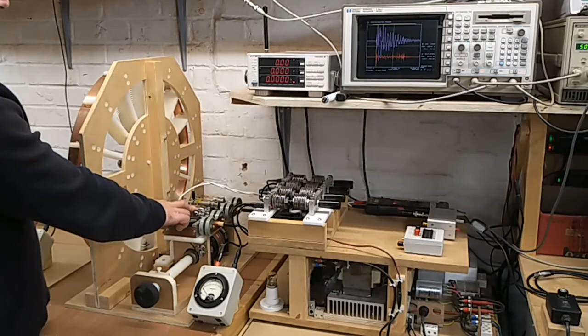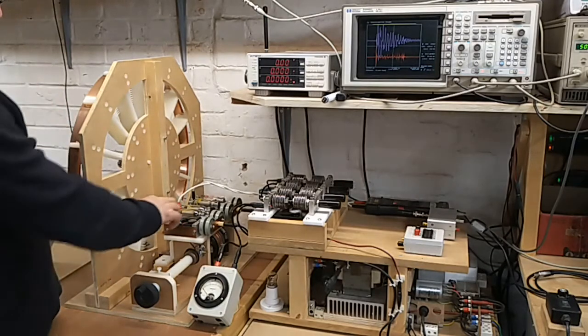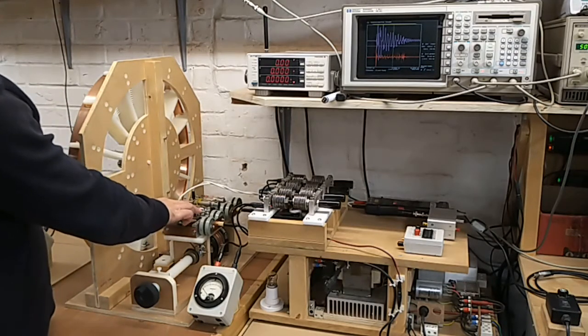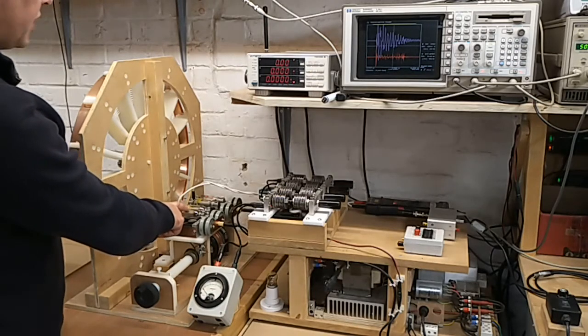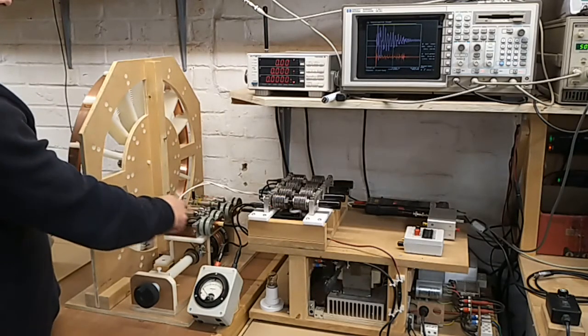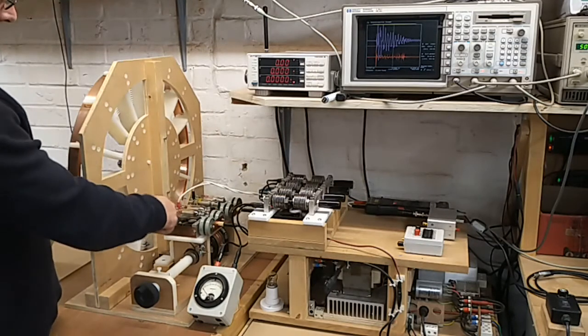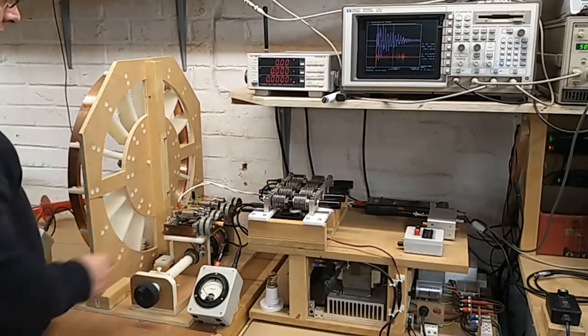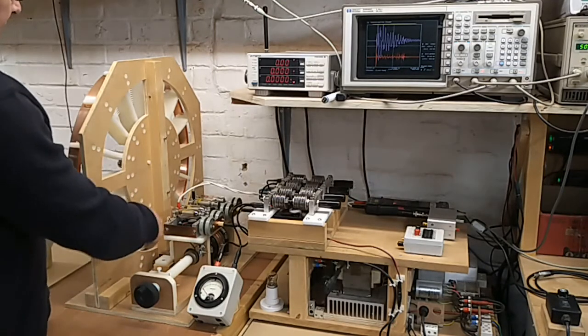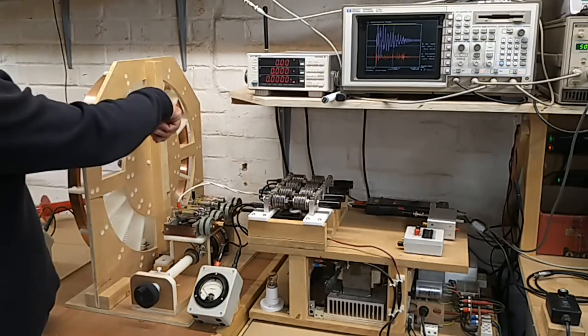They have a trigger voltage of somewhere around 2.5 kilovolts, but their impedance is quite high, so they will considerably reduce the current, the oscillating currents in the system, which is why we have a shunt in this experiment here. So then that's fed down to the primary.